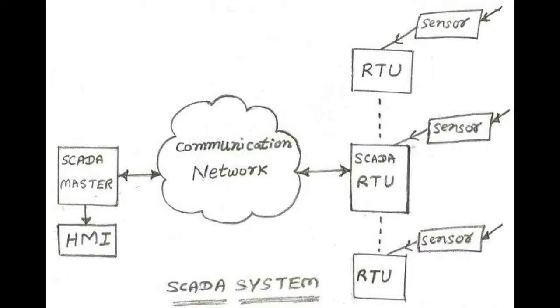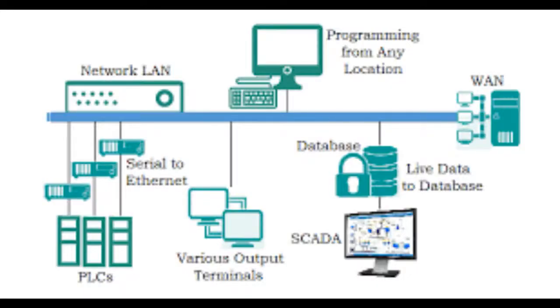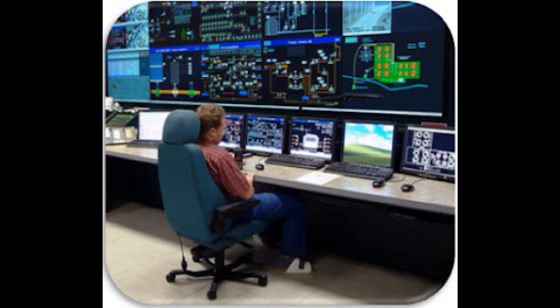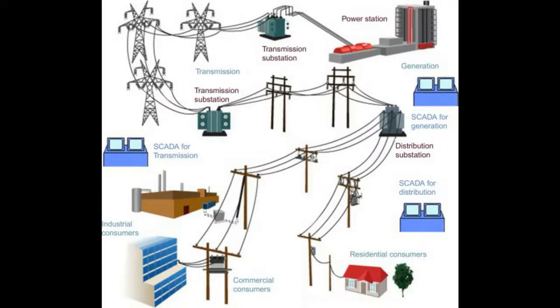Different operating skills are required, such as system analyst and programmer. With thousands of sensors, there is still a lot of wire to deal with. The operator can see only as far as the PLC. The PLC SCADA system has complexity of system hardware and depends on modules, which leads to low reliability.